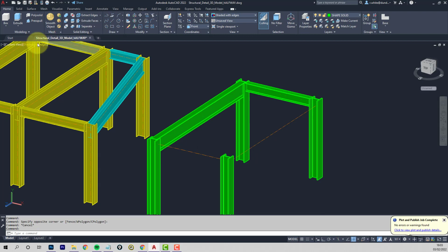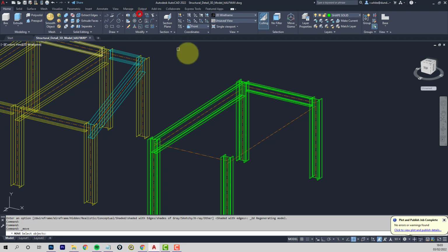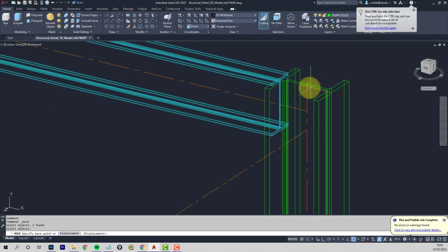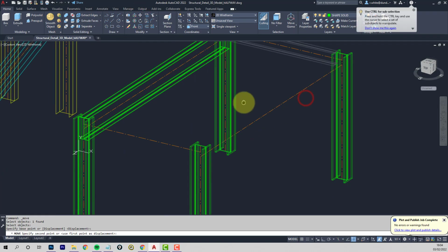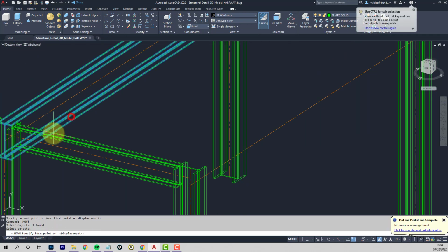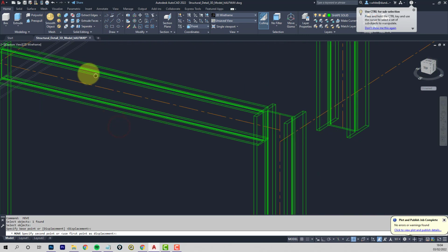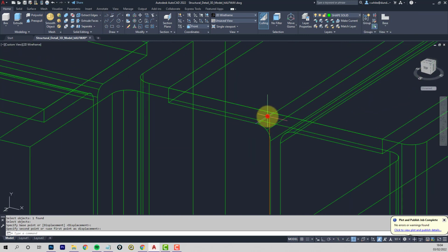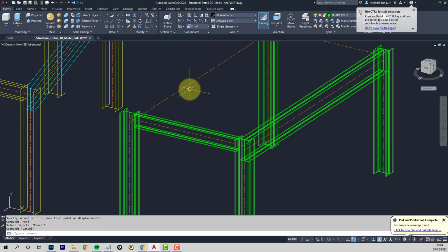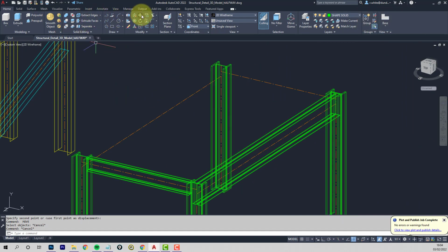Okay, we've got a bit of copying to do, so let's go back to 2D wireframe and copy this beam first. Let's go from the setting out point to the setting out point and copy this one. Similar way, setting out point to setting out point. Could have copied it. Oh, I've moved that. It's off. Moved both of them. Oh, idiot. Should have picked the wrong icon. Sorry. Move and copy right next to each other. So copy. Let's just do it numerically then.